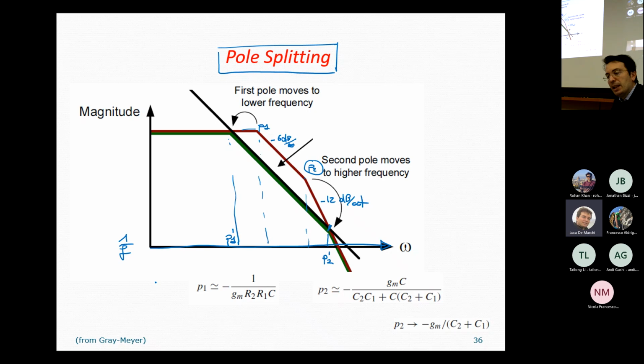Okay, we have to combine the information related to the input-output swing, the slew rate, the DC gain, and the phase margin achieved by the circuit to set the dimensions of all the transistors in the circuit, and also set the value of the compensation capacitors.